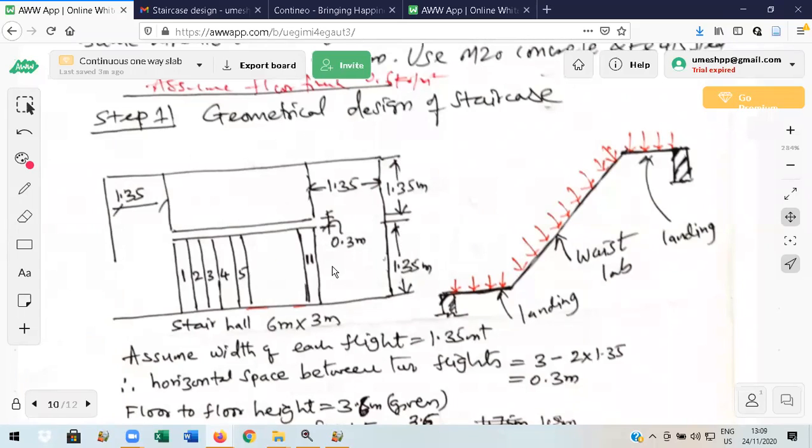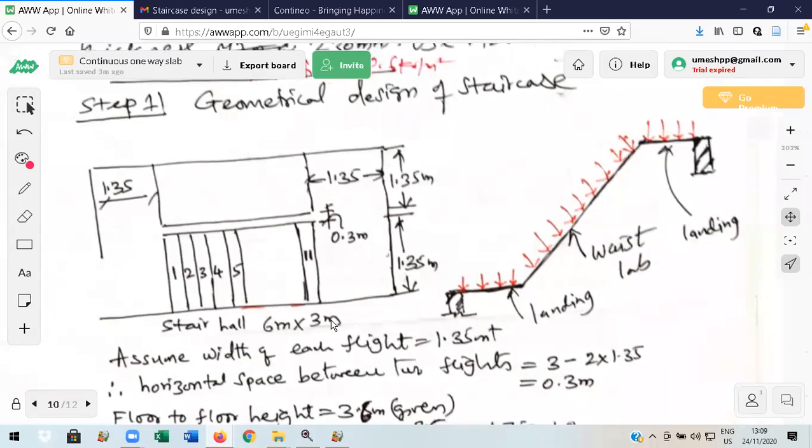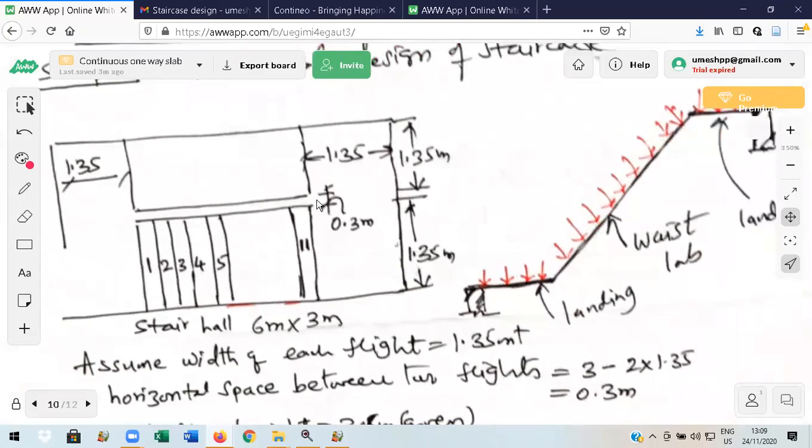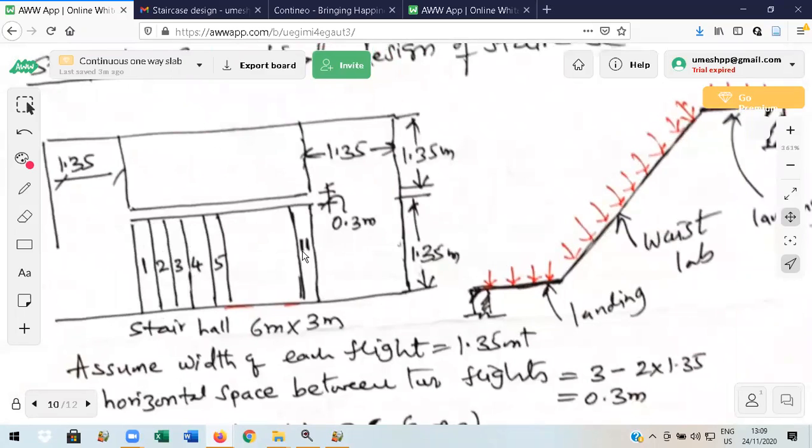Okay. So when you start planning the geometrical design, you should start with the gap. How much should be the gap? Then only you can finalize the remaining. You must see that it should not be less than 1 meter at any cost. Preferable is 1.5. If at all the dimension was 3.5 meter, I would have adjusted that one. Now here 0.3 I have taken. You can very well take 0.2 meter here. Nobody will object. The design slightly changes, that's all.